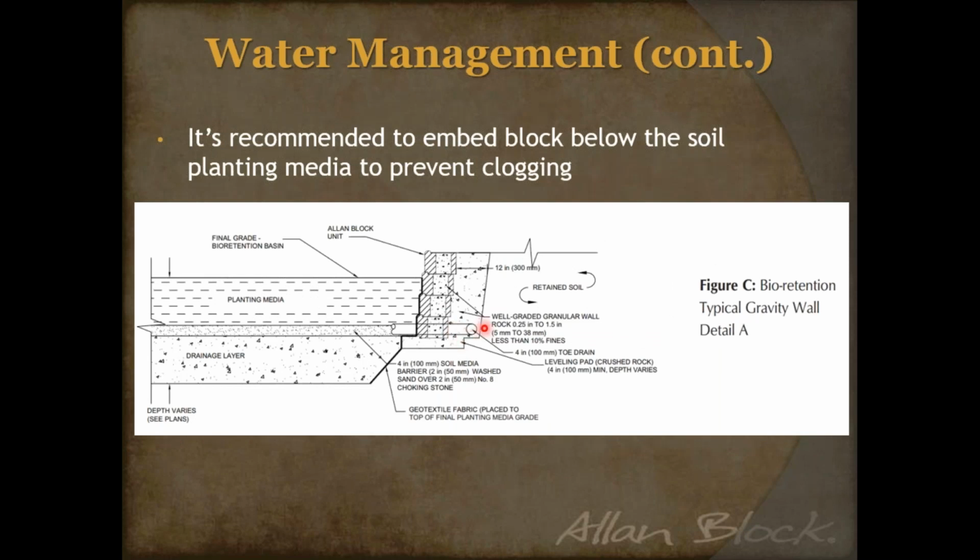Here's a gravity wall, same application. We're going to bury enough block; a smaller wall doesn't matter. We're going to just make sure we bury the block, bring the pipe in, and get that pipe into your drainage zone right away, not in and below the soil media.